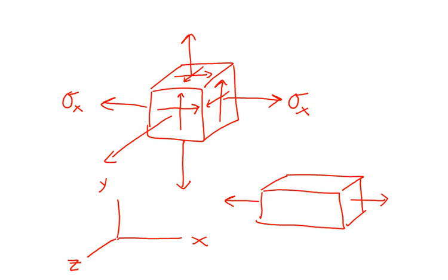And then due to sigma sub y, it will elongate in the y direction, and due to sigma sub z, it elongates in the z direction. And of course, if these were compressive stresses, then instead of elongating, it would shorten in the x, y, or z directions. So normal stresses result in a part just getting longer or getting shorter. That should be fairly intuitive.